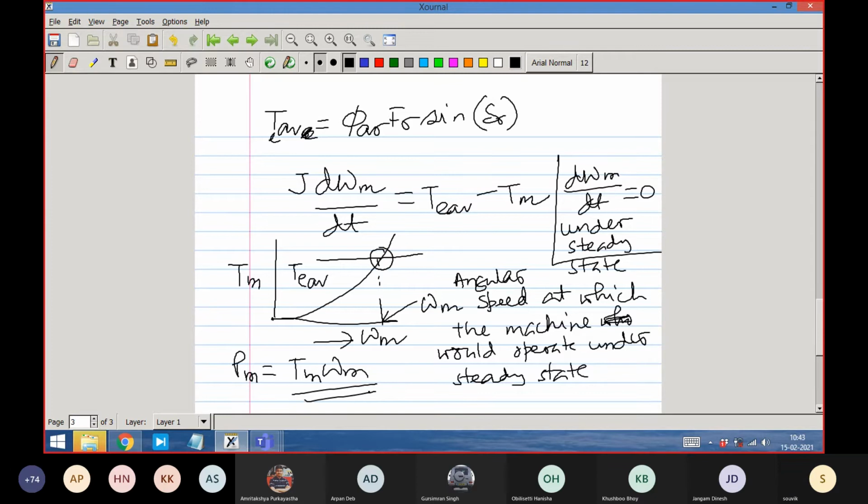Yes? Yes, sir. So you can apply voltage. So let us see how voltage dictates. Can voltage dictate any one of the things? Can it dictate FR? Can it dictate phi AR? Can it dictate sine delta R? Can it dictate anything? Tell me what it dictates. One thing very clearly. The moment you say voltage, voltage means voltage magnitude plus you are also saying frequency. So what are you dictating then?